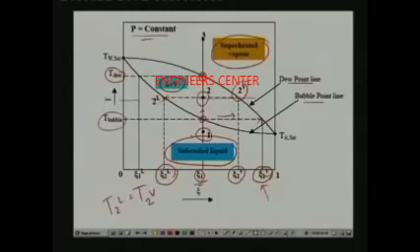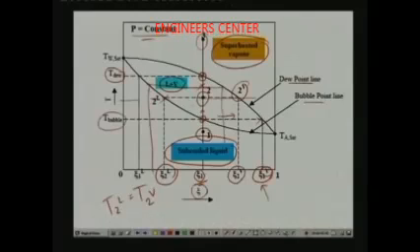It is interesting to see that the concentration will be different in the two phase region. Once you come back to the superheated region, because of the conservation of mass, the concentration again remains the same. So once you have the charts, you can find out at any point, for example at some other point, what is the concentration of the liquid and what is the concentration of the vapor.